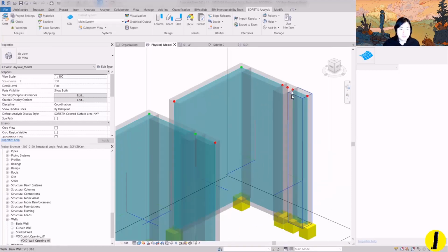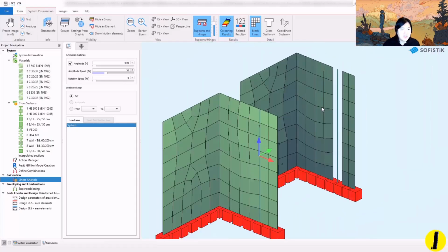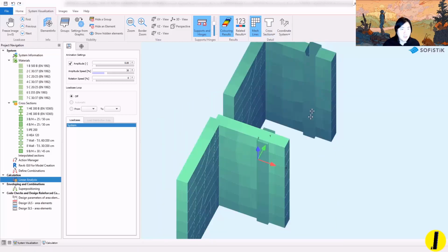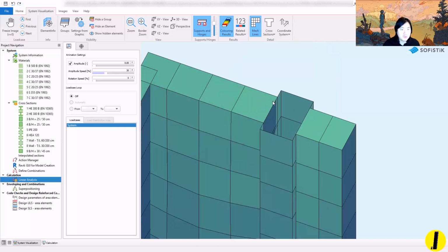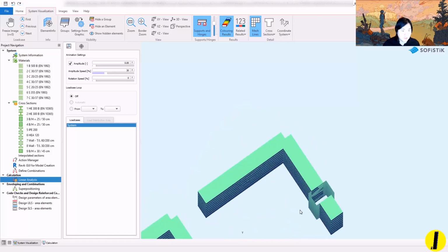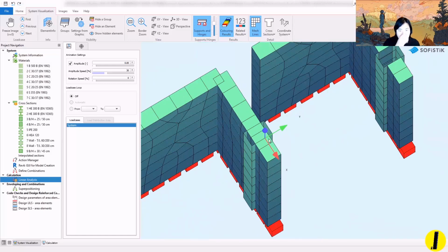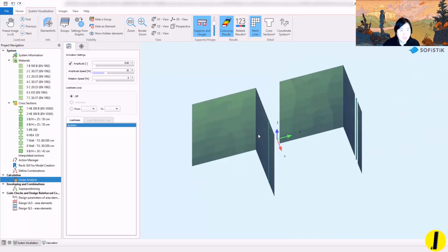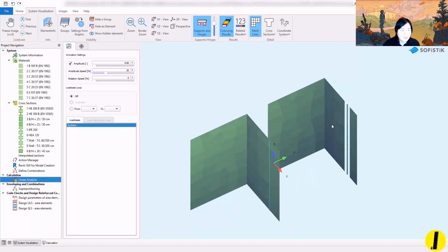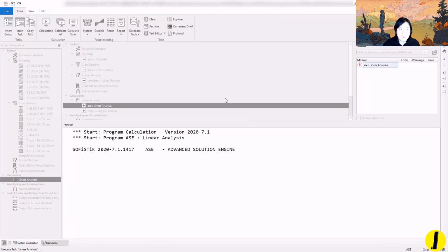I'm curious because when you look at the static mesh, they are different. But when you give the cross section, maybe the right hand side makes more sense because you have the column thickness, and at the same time the wall is joining there, whereas the other, they're kind of clashing with each other. But the static mesh on the left side looks correct to me, but SOFiSTiK seems to do both calculations correctly. So let me do linear analysis of that.